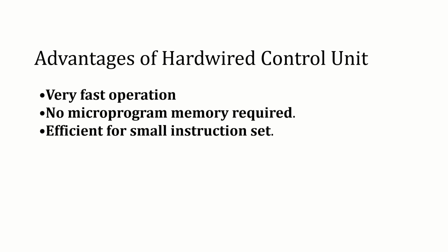There is no need to fetch microinstructions from memory, so the execution speed is very high. No microprogram memory is required. It reduces memory usage and makes the system simpler.